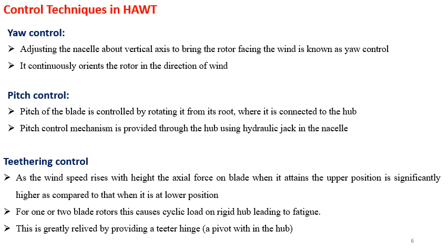At wind speed exceeding the rated value, the rotor speed is held constant by automatic adjustment of the pitch of the blades. At very high wind speed, the blade is feathered, as in aircraft, and the rotation ceases.